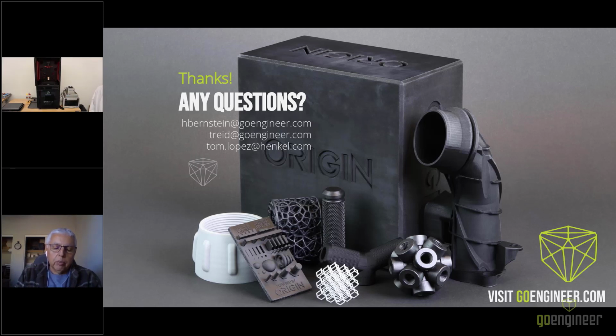Part of a validated workflow is the correct printer, the correct material, the correct settings on the machine, but also the correct cleaning of the part. This is something that Hunter spoke to earlier: cleaning the part, allowing the solvent to flash off for a certain amount of time so there's no solvent left in the part.